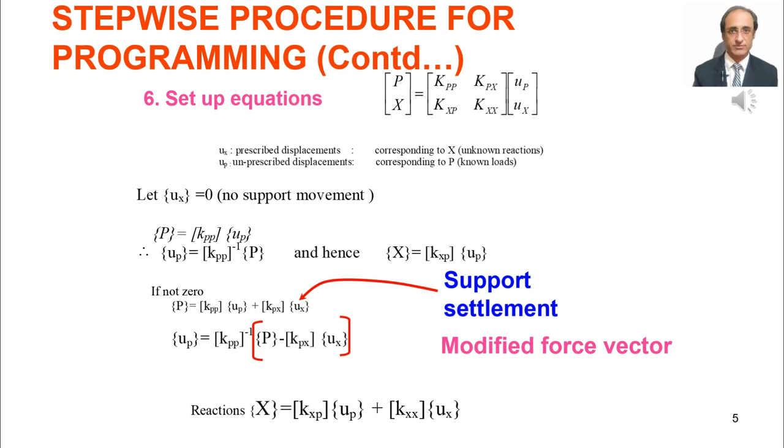Next question is, what additional information do we need to find out? We say that we are analyzing the structure. So far we have obtained the displacements of the structure. We have also obtained the reactions. What else do we need to complete our analysis? The answer is that we need to obtain the member forces, because it is based on member forces that we can design the structural members. So we'll cover in the next slide how to obtain the member forces.